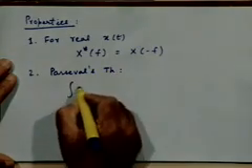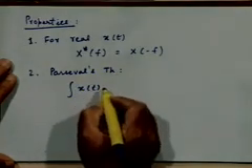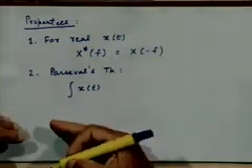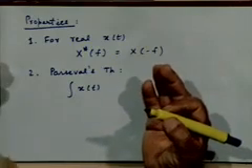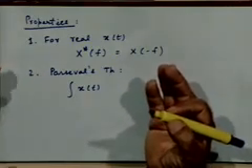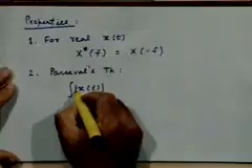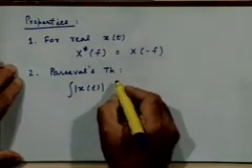Now it makes more sense to talk about energy here, because the existence of the Fourier transform is only for finite energy signals, although we can extend this definition to periodic signals as a special case. But generally Fourier transforms are defined only for energy signals, because that's a condition we discussed. Right? They should be square integrable. Right? So it makes more sense to talk about energy here.